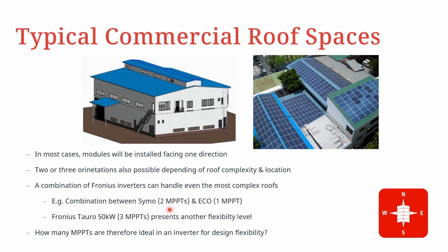Whereas our new Fronius Tauro 50 kilowatt standard, which has 3 MPPTs, presents another flexibility level. So it's having one inverter that has 3 MPPTs with a 50 kilowatt power class. So how many MPPTs are therefore ideal in an inverter for design flexibility? So next I'll be handing over to my colleague David, who will be continuing.